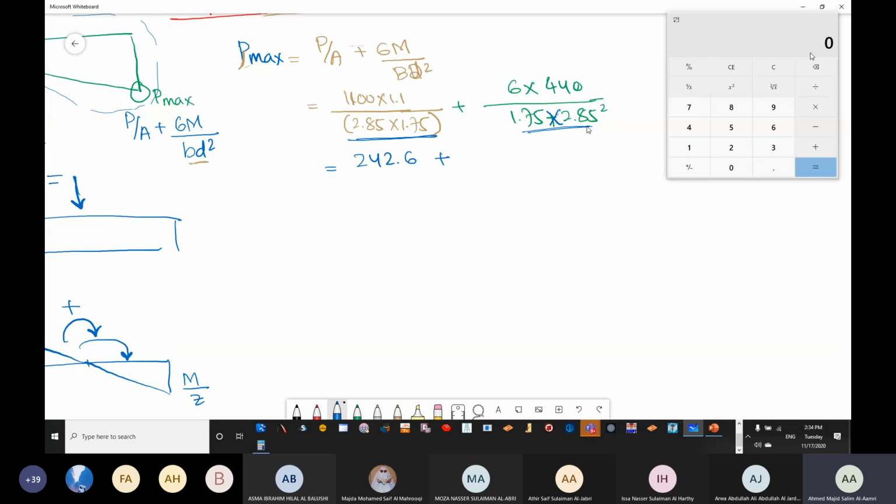If you remember, when we are checking the pressure, we check unfactored. This is what we have done in isolated footings, if you remember. When we start calculation for the bending moment, at that time, we take the ultimate. We said safe bearing capacity is already factored. So 185.727.